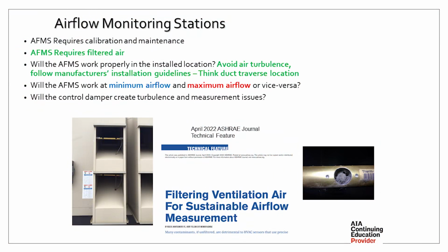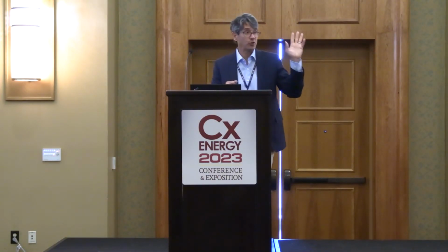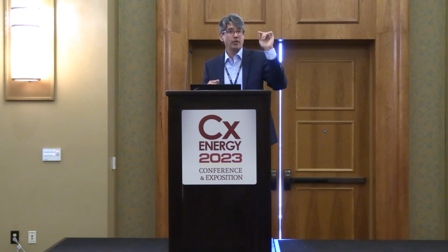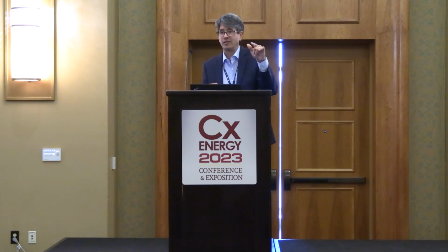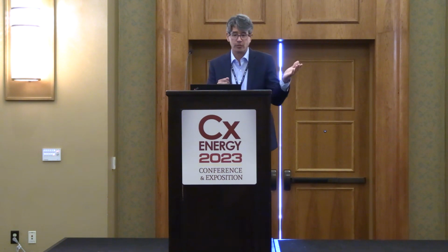Don't get caught in the lovely thing of airflow monitoring stations. Hey, you know what? We can't measure there. We'll just stuff an airflow monitoring station in that duct. We'll be fine then. They need to be calibrated. They need maintenance. They need filtered air. And they need a good place to be put with a good velocity profile. So when you look at where to put that airflow station, a great place is where you do a duct traverse. You need a good even velocity profile, and you need to make sure you maintain that for that airflow station.